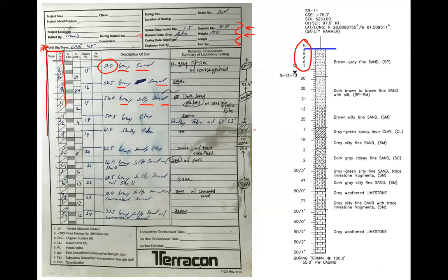So by looking at that video, maybe because it's super early, you guys haven't thought this yet, but you can probably see there's a lot of variables involved. What would happen if you're 100 feet down and you have 100 feet of rod on that sampling bit? That 100 feet of rod is going to be really heavy. So that's going to change the amount of energy that is actually applied through that hammer, right? Compared to something super shallow. Some of these hammers are different sizes. So the size of the hammer is obviously going to change the number of hits, the ease of it to penetrate through it.